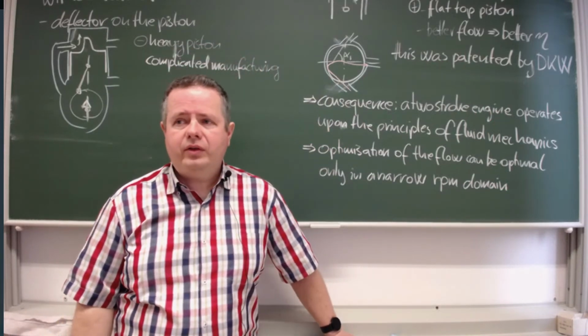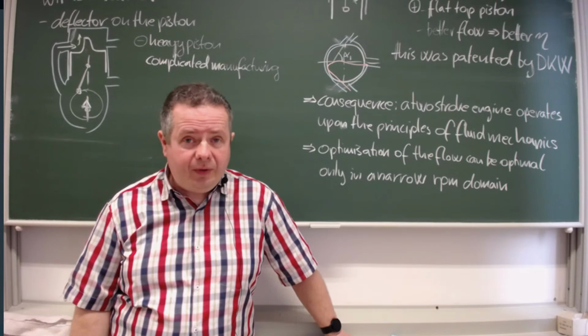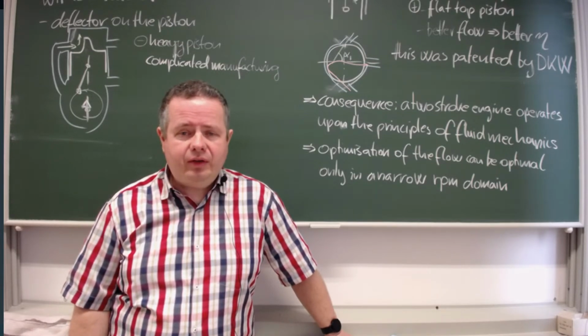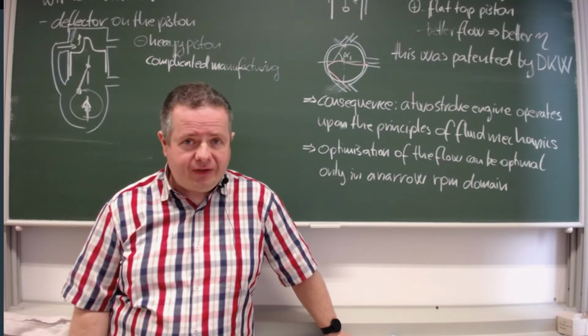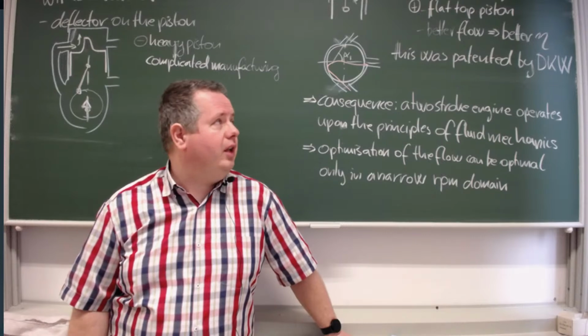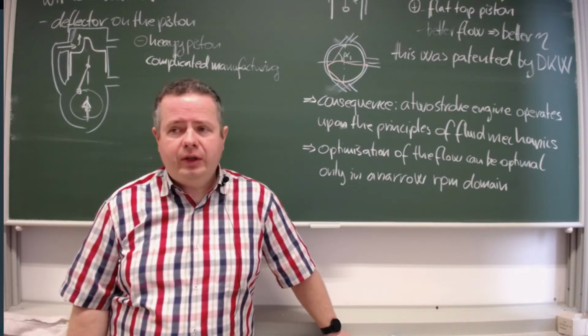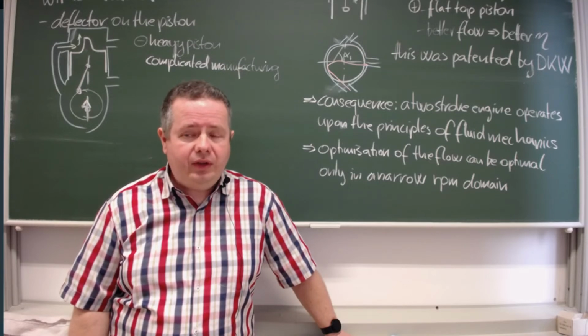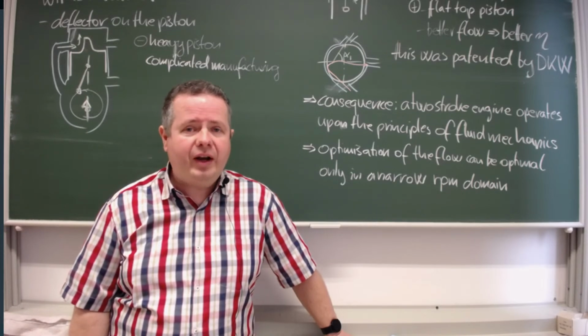So, as you are working in fluid dynamics, you have frequencies and critical speeds in your system. And by orienting the angles alpha 1 and alpha 2, you can make good things, but these good things depend on the speed of your gas flow, and the speed of your gas flow is linked to your RPM.